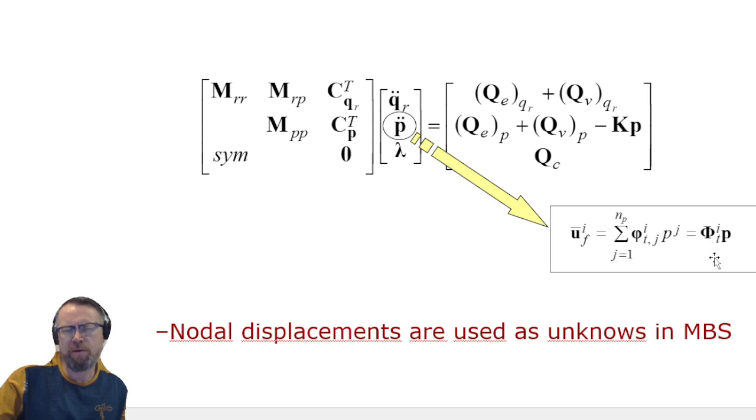This one you can get from the Craig-Bampton method, or just an eigenvalue analysis. It doesn't really matter how you do it, but you have access to this information. And once you have the modal coordinates solved from the equation of motion, you can go back to the nodal displacement. Okay, nodal displacement, this is clear. This is nothing new.